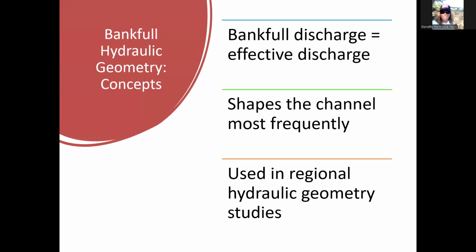So bankfull goes all the way up to the riverbanks, okay? So that discharge equals what's called effective discharge. And we just learned about this in the previous chapter. It really causes the most shaping of the channel, right? So you see this in a lot of our geometry studies because we're trying to figure out what actually physically shapes the channel. So the morphological changes, that's what we're looking at.